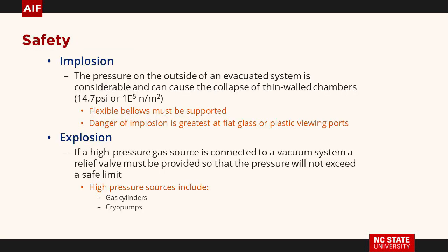Safety. Pressure on this chamber can be enormous, and we'll show you some calculations and examples of that. If you've got a flexible bellows and it's not supported, you start pumping, it can move. I've seen a mass spectrometer nearly ruined that way.